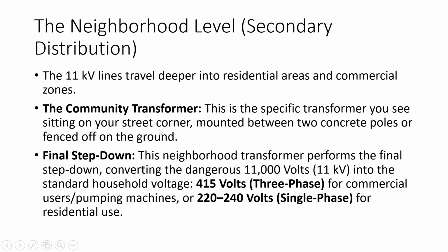Now this community transformer is where we're going to do the last step down, because this 11 kilovolts of electricity is still what? Too high for you to connect it directly into your house. So your community transformer is now going to step it down to a voltage that your house can use comfortably, so that your appliances will not start roasting or will not blow up or get burnt. Now that is what we mean here by the final step down.